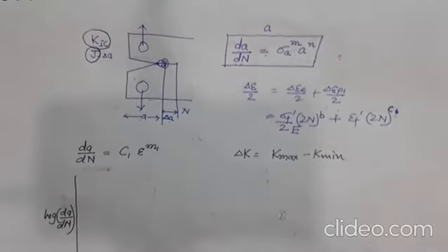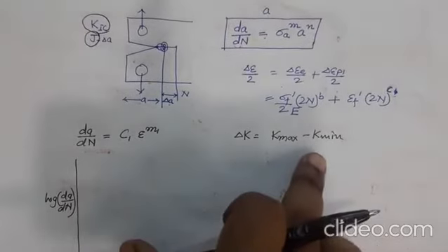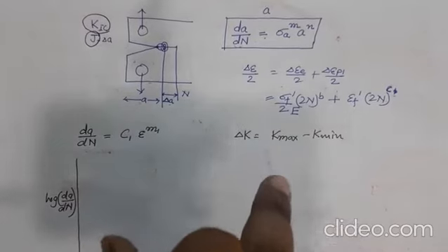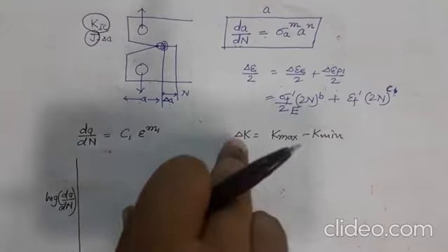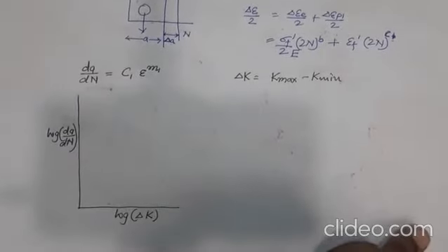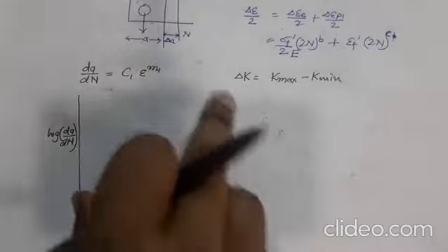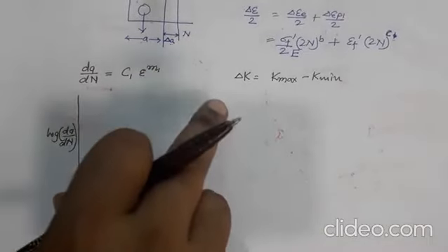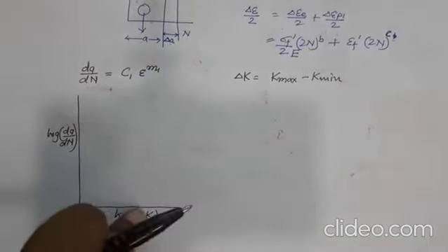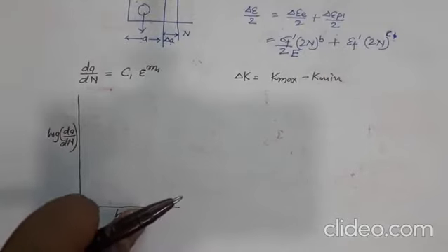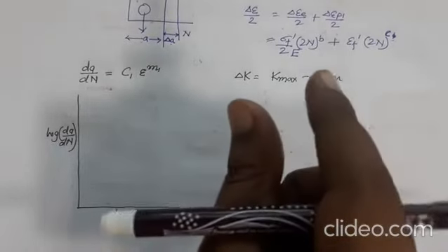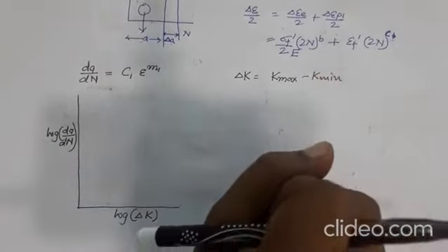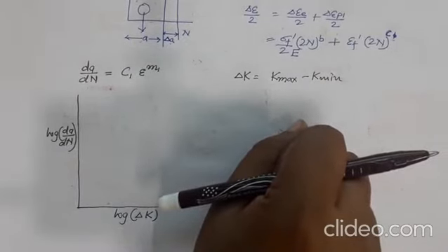This concept is applied on structures, and we assume that we always have some cracks inside our structures, and that will lead to failure, and only then we can apply this. In laboratory testing, we must have a pre-crack in our specimens to find out this plot, and in a structural component, from this we can do a reverse calculation and find out how small a crack in the system will not lead to a catastrophic fatigue failure.